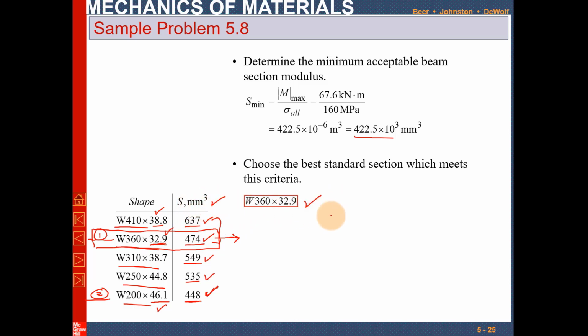So this is how we design the beam. Again I will conclude: we have a beam under a given loading, and we are asked to design the beam. Under the loading, we have to draw the shear force and bending moment diagram, or only the shear force diagram, and by using it we can see where the shear force is minimum or zero.